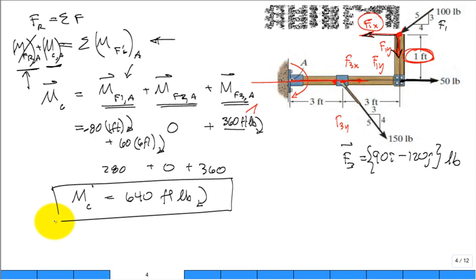Okay. So that is a vector? Yeah, that's a vector. So you don't need the IJK? Well, we're doing a 2D, scalar analysis of this problem. If, like you had it, it would be negative 640, I think that's the answer you already had, didn't it? In the K only, and nothing in the I, nothing in the J, and then you would have units out here of foot-pound as a vector. You wouldn't need to specify direction in that sense? Because it's in the negative sign, yep. That conveys the direction.